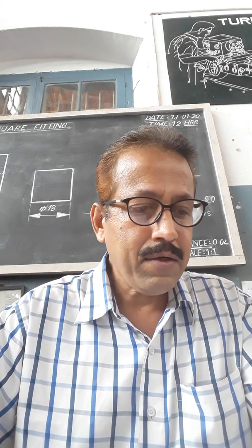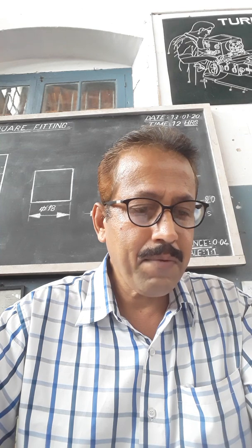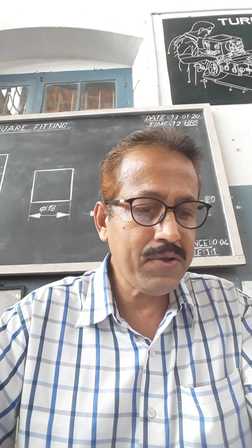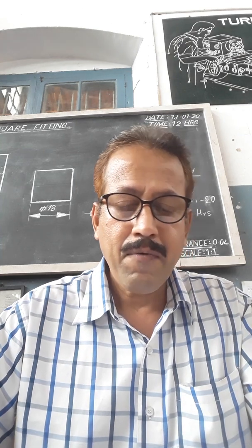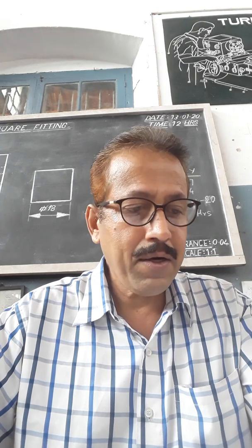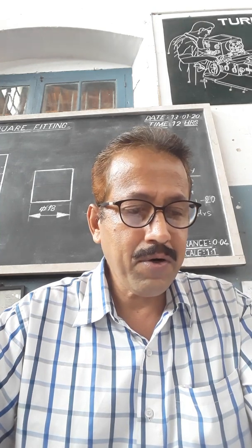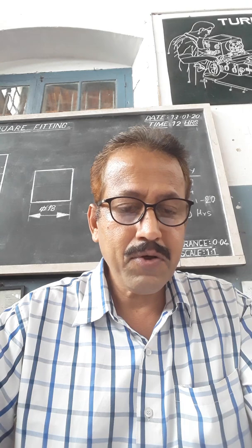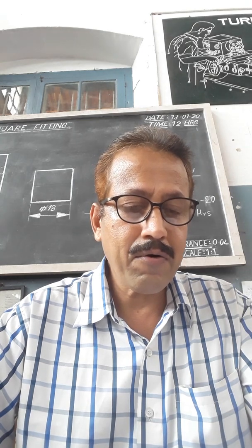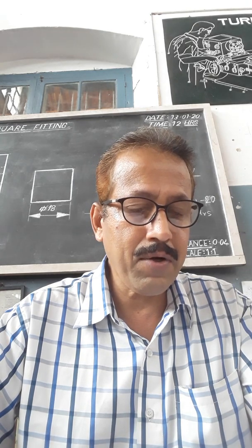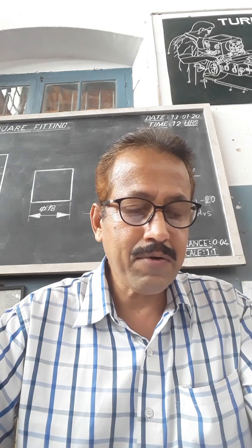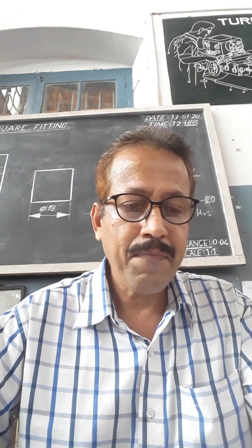Care and maintenance. Keep the pulley faces and belts free from foreign material which may cause slips. So for care and maintenance of the belt, the first point is a very important point. Always the pulley should be dry. No oil, no grease, or any other foreign material should be on the pulleys or grooves, because that will make the belt slip.